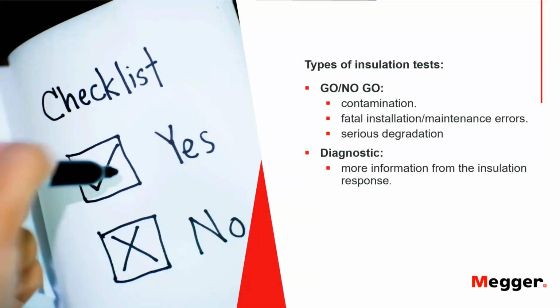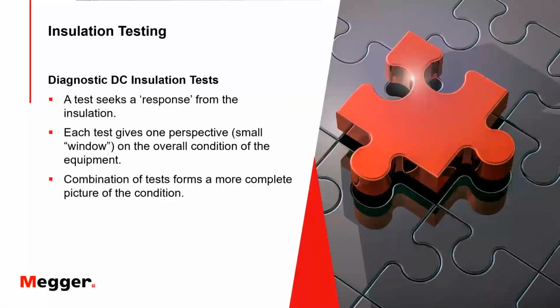Remember, insulation resistance readings work like a car odometer, but in reverse. They start out real high. Brand new equipment is likely to be off the scale of your tester, but over time, the resistance gradually drifts down. And so it's like a car odometer in reverse. You want to see, where am I on the life cycle of this equipment? If you're up in the teraohm range, you don't have anything to worry about. If you're getting down in the low megohms, then you have to start taking preventive procedures. Next.